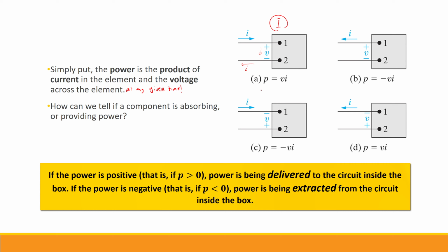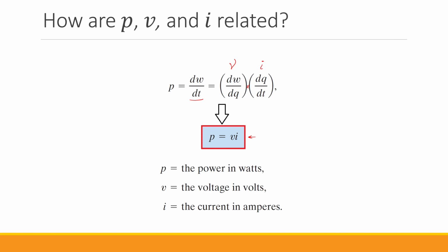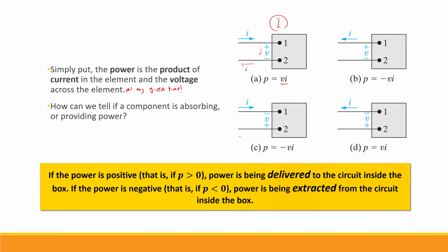So based on this, for the equations, we use the positive values for both current and the voltage. So if we do that, power equals voltage multiplied by current. It should be quickly pointed out that in this equation, we consider the generic voltage and the generic current, right? We don't consider their directions. If we want to consider the directions, we should follow the passive sign convention.